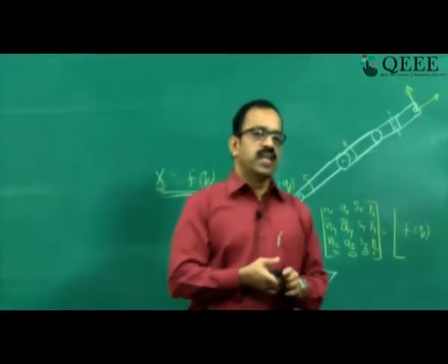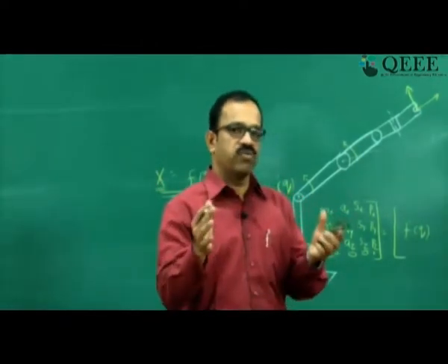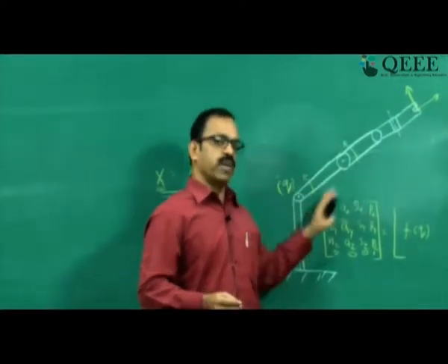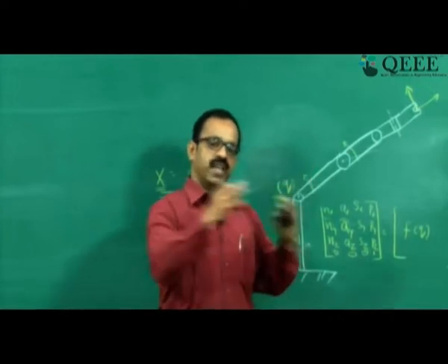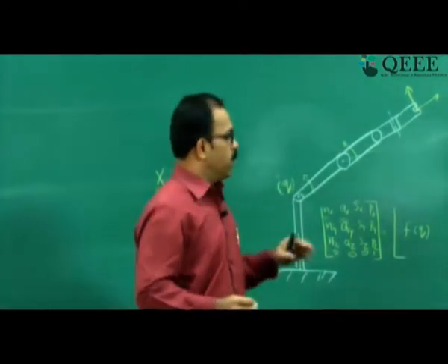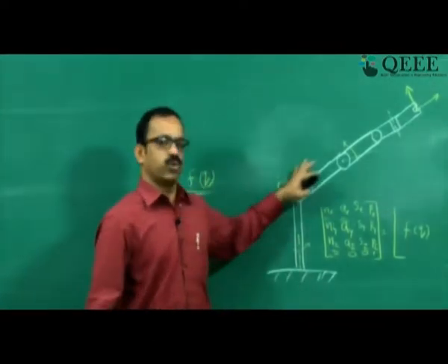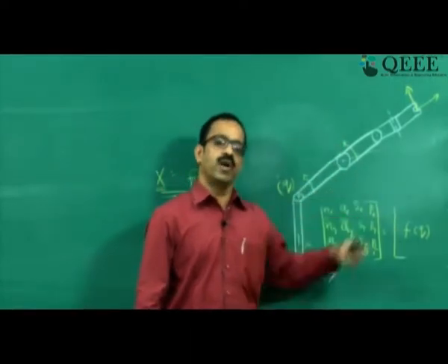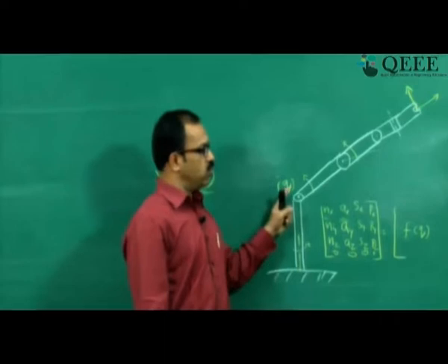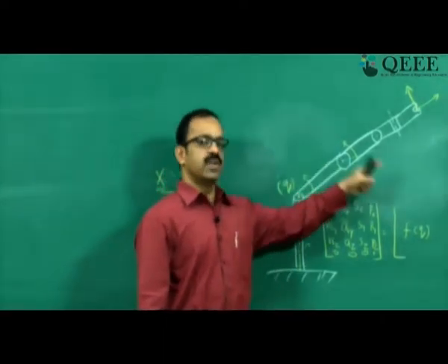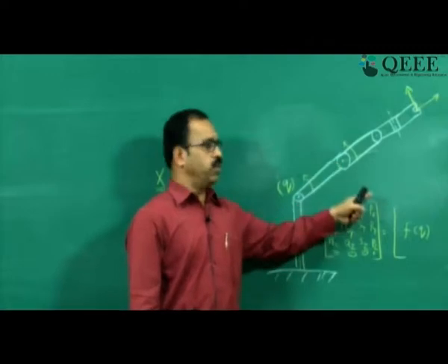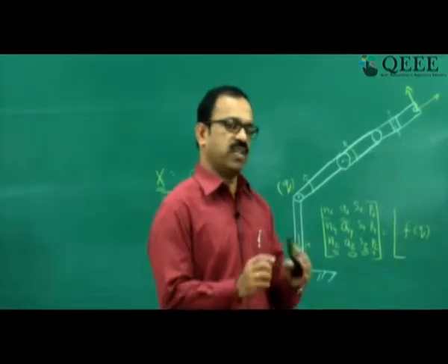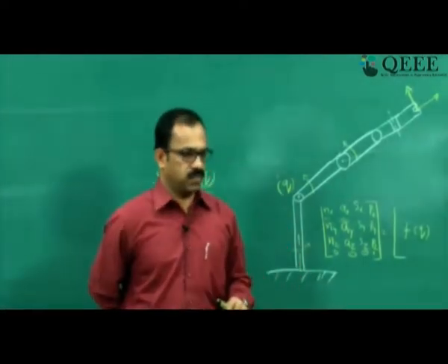Another problem is that there is no way to get a systematic closed form solution applicable to robots in general. It was possible to get a general solution for the forward equation, but for inverse kinematics there is no general solution for any robot. For each individual robot, we need to find the solution for that particular robot. Depending on the robot kinematics and configuration, the inverse solution varies and the way to solve the problem also changes, and therefore we cannot have a general way of solving the problem. So there is no generalized solution for inverse kinematics.